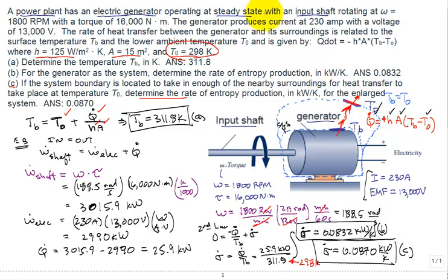And then you say, why is that larger? Because in this space right in here, there's heat transfer from a higher temperature coming in to a lower temperature going out. If you just focused on this green hatched system, maybe I should try and draw it like this. It's just a system of air where the boundary on this side is higher temperature and the other boundary is lower temperature. You have a heat transfer through that system. Well, there's entropy generation there due to the irreversibilities of heat transfer. That's why it's a little larger. But anyway, that's the answer for part C.